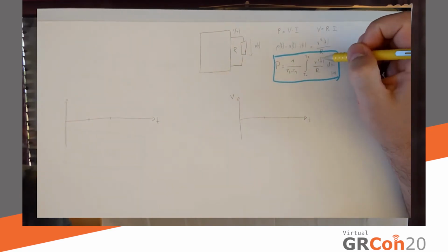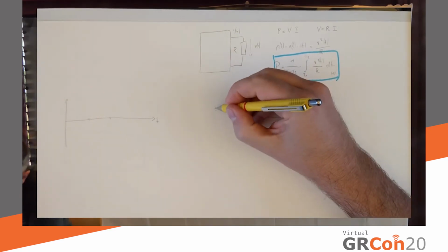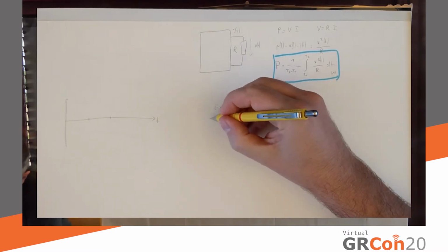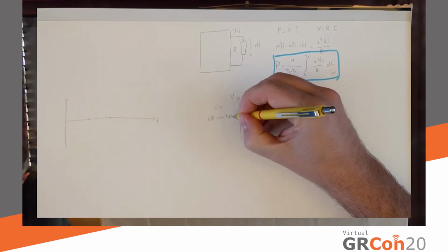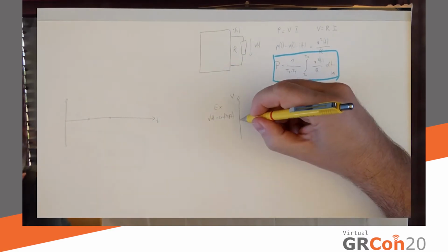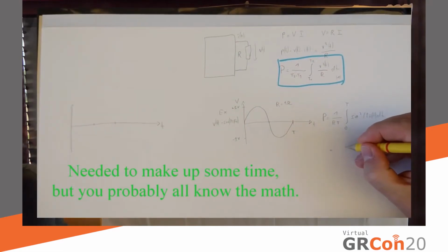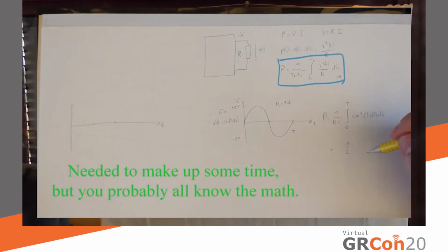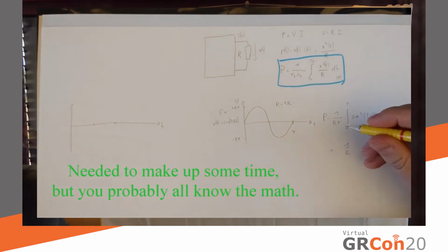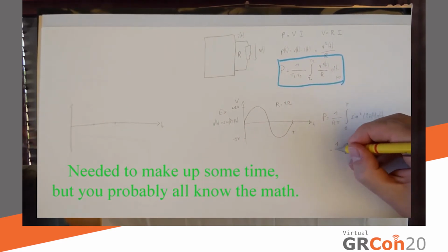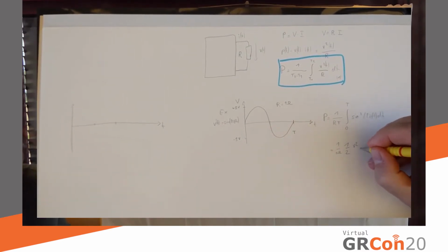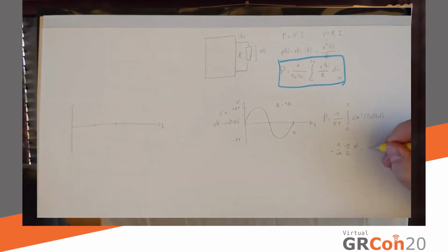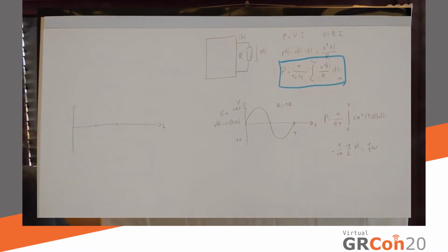To illustrate it better, let's say V, as an example, equals a sine wave. V of t equals sine 2 pi f t. So the average of the sine wave squared goes to 1/2. Now, a physics teacher might say 1/2 watt, and the answer is also 1/2 watt because R is 1 ohm, so 1 over 1 ohm. The unit of this here is volts squared over ohms, which equals watts, so in this case we would have 1/2 watt of power.